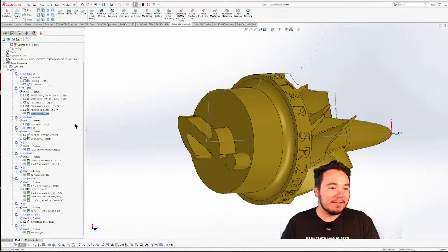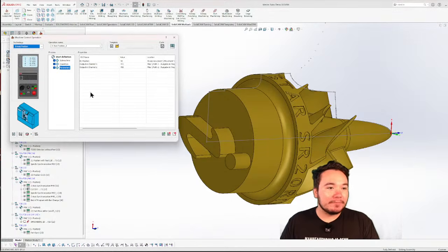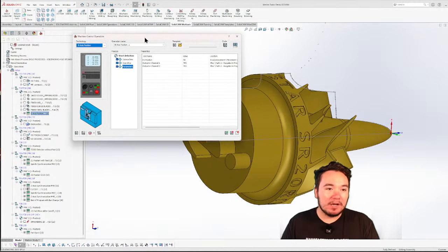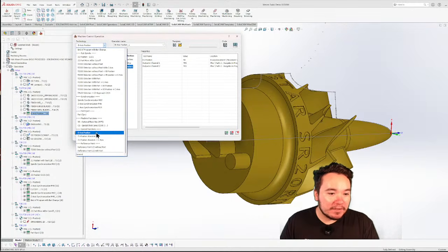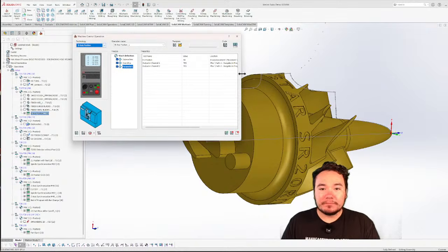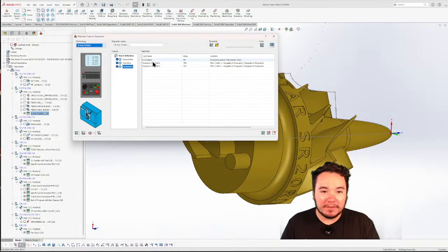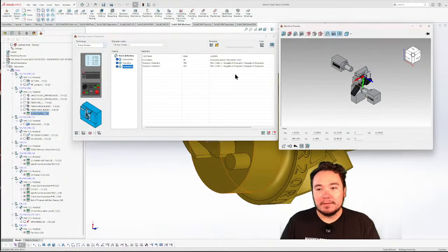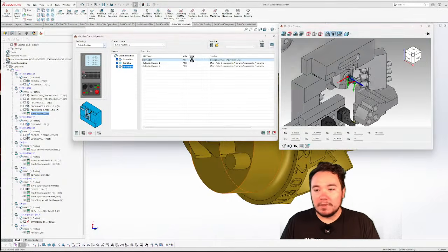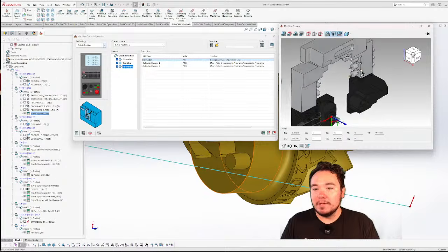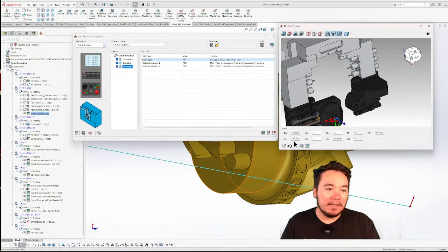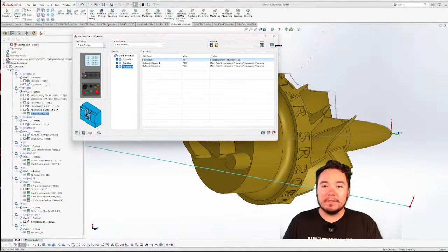So we want to use the B-axis head position, and so you just come over here, you can right click, you can hit add MCO or machine control operation, and then I went in here and selected B-axis position and what channel to output it to. It did 1 and 2, and then I made sure that it was 90 degrees as well, and you can see that right here. When I click on here, it should home the B-axis for us. And the next thing we got is the engraving.